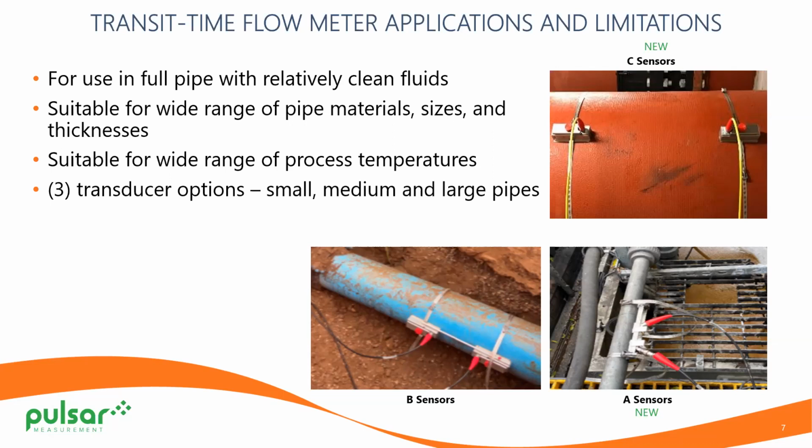these were a great new addition, because you can imagine a large transducer like you see on the top there, or down to the left, trying to fit the curvature of a small pipe. That was very difficult. With the new small pipe transducers, that's done very easily. And I think we're talking all the way down to a half inch, even sometimes down to quarter-inch pipes. So that is relatively new, along with our large pipe transducers.